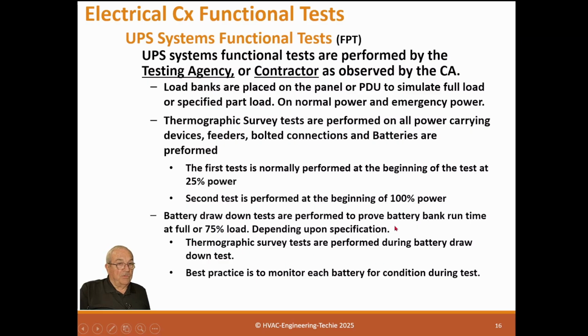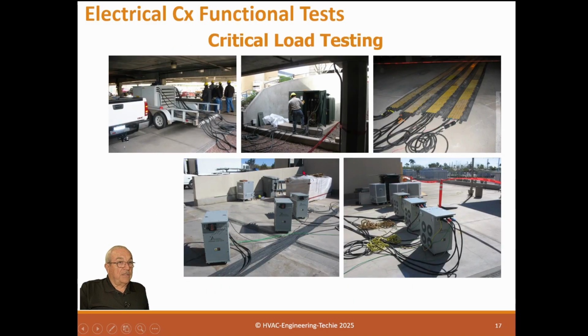And one reason we don't normally use a 100% test is we don't want to stress the batteries very badly. So we basically use 75% load and run it down to its time. Provide test scripts with actual data for documentation of the test.